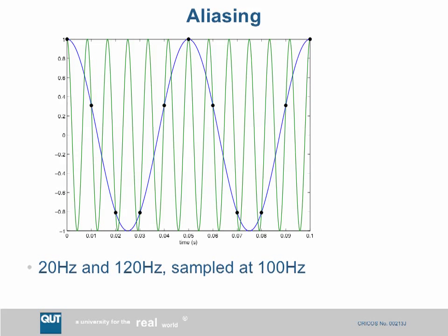So there are some rules of thumb when it comes to digitizing systems. Typically, you want to aim for a sample rate up to maybe 30 to 50 times the frequency that you're interested in, right? So that's a rule of thumb. If you do that, then you can use the simplest possible method to discretize your system, that backward difference equation that we talked about the first time we discretized the system, when I made that substitution. That will work well if your sampling frequency is high, 30 times the bandwidth.